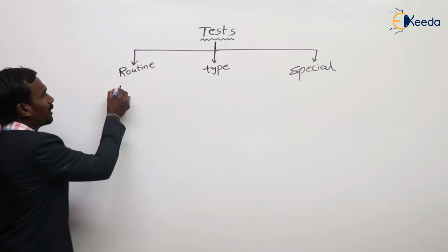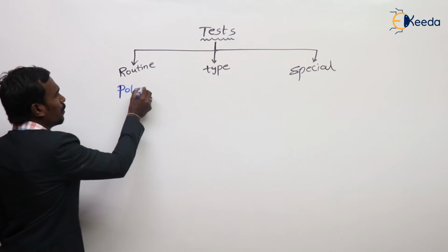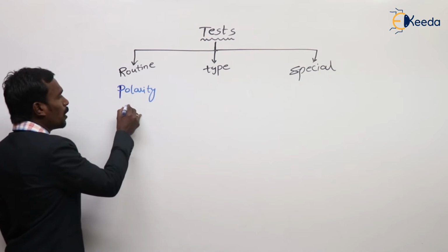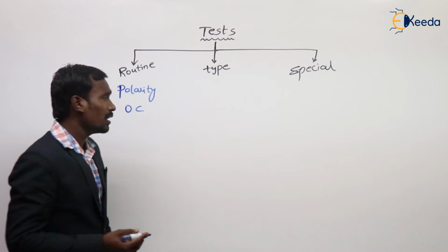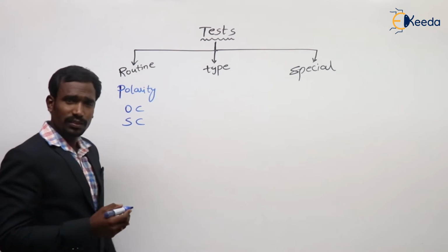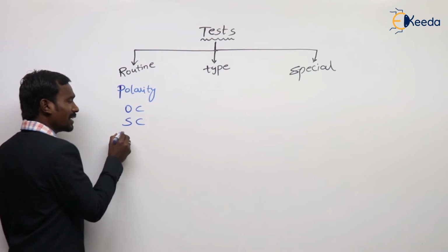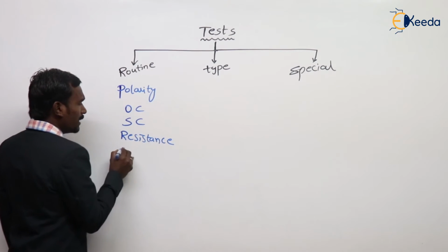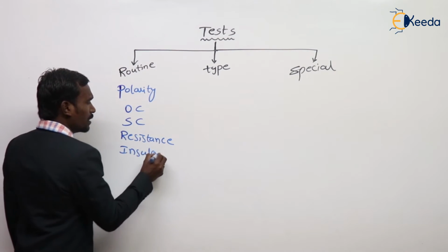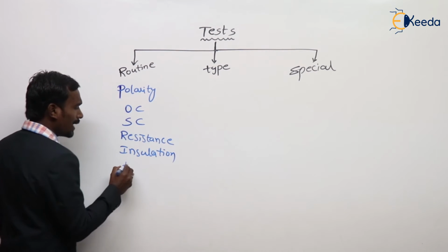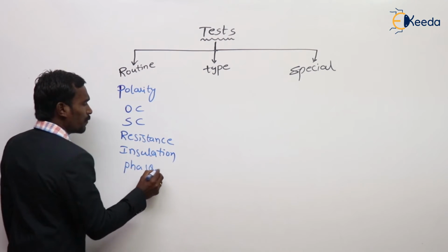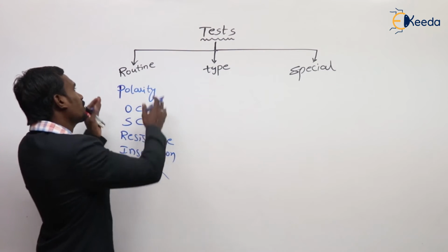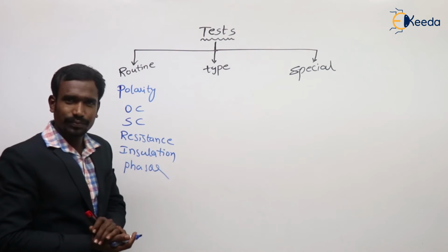Generally, the polarity test, because we should know the polarity for parallel operation, and the open circuit test, short circuit test, resistance test, insulation test, and phasor identity test. Like that, many tests are called routine tests.